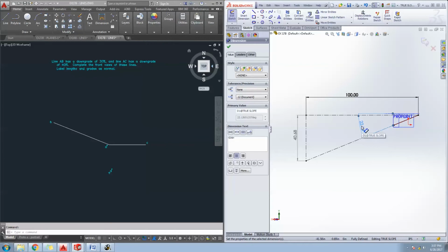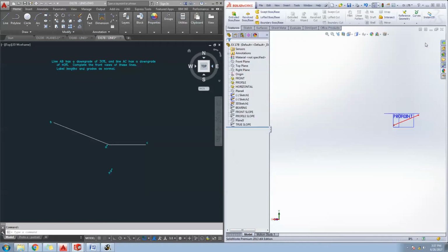That's the slope. This is another way of writing the slope, and it's a special way, and it's called the grade. You can think of it as a dy over dx sort of situation. You're going to go out a run of 100 units, and then down however many units it takes to meet up with that line, and you're going to call that the grade. And you're going to see a little bit as we move into an example.